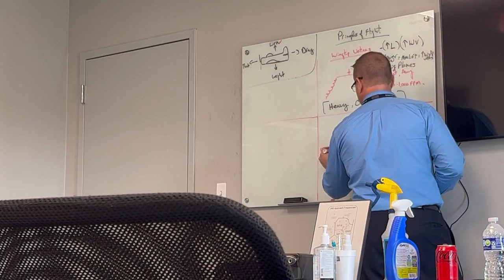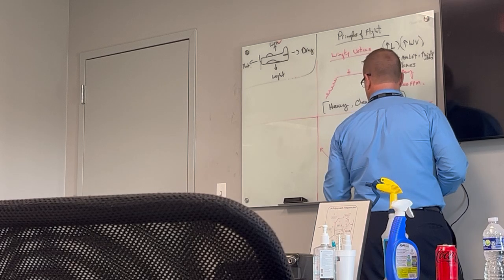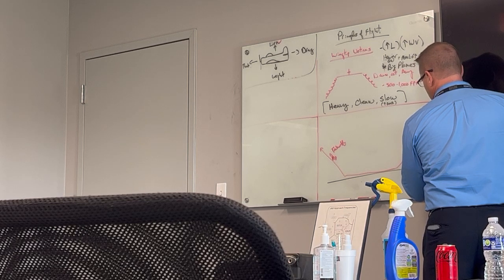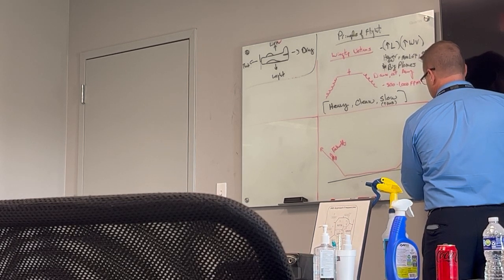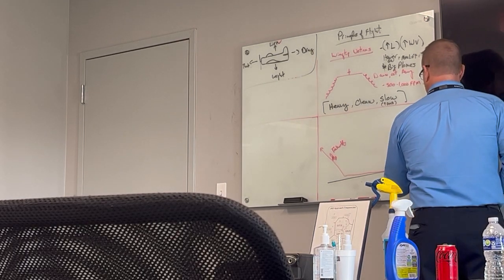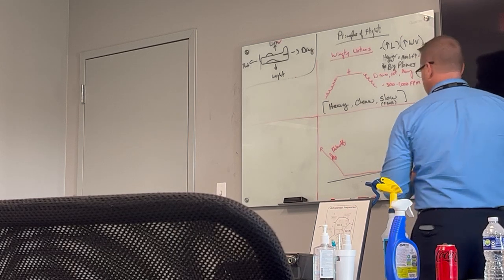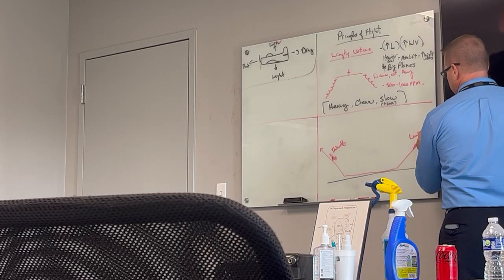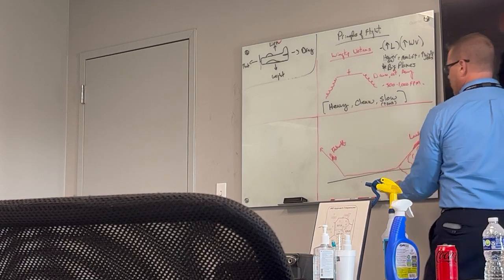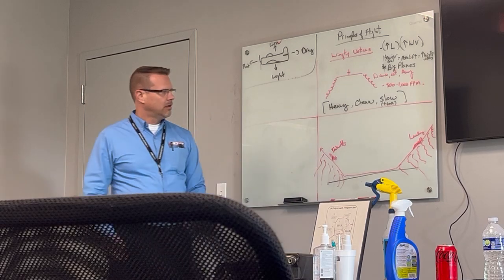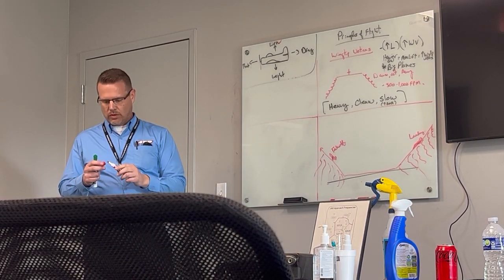So at takeoff, and also we're worried about it when we're coming into land and we're relatively slow. So takeoff and landing are the two times in which we're worried about these wingtip vortices the most. And again, if this is the flight path of our jet, we know that the wingtip vortices are falling down underneath their flight path. So this area down here, underneath there, is a no-go region. That's a dangerous area. We don't want to be there, right?